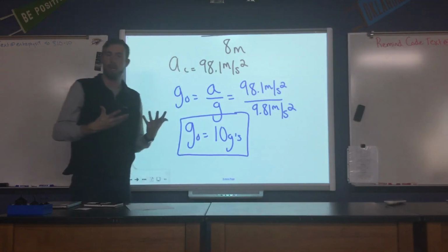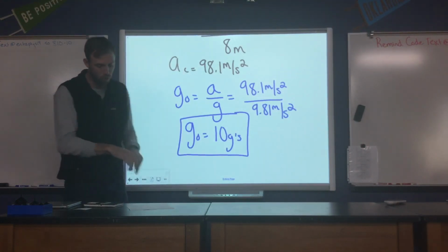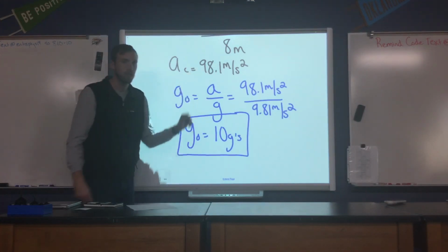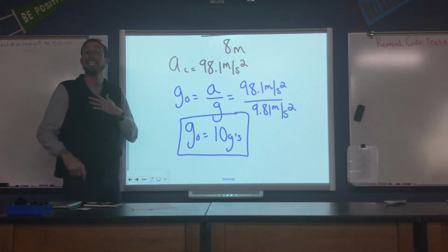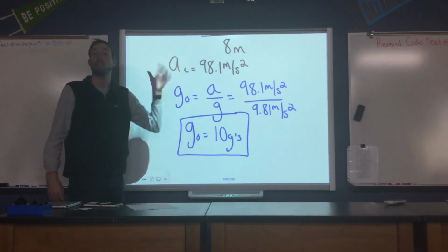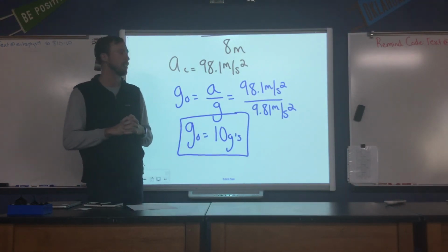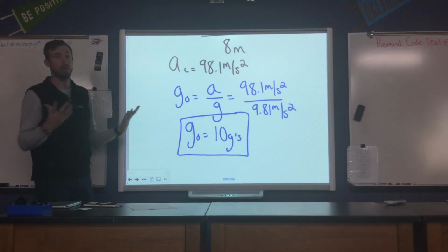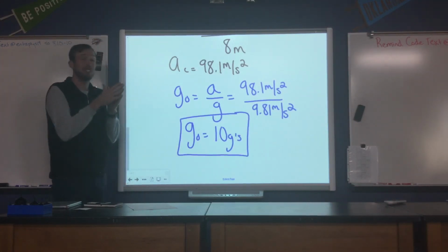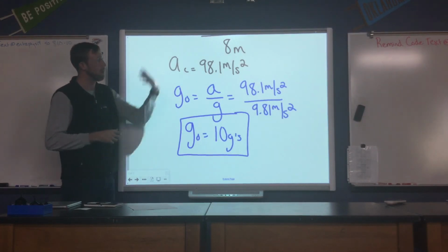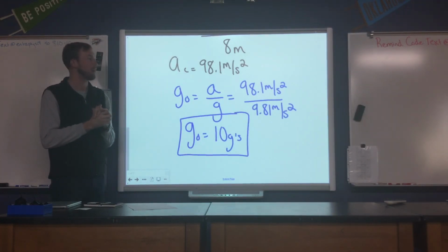Obviously, it depends a little bit on the time in which they're exposed to this g-force. The chart that you're provided with in the problem tells us this would likely lead to some dizziness and loss of consciousness, which we probably wouldn't want to shoot for in the roller coaster design. So in order to maybe make this design safer, we could increase the radius or lower the drop height. That would maybe lead to some safer conditions for the riders.